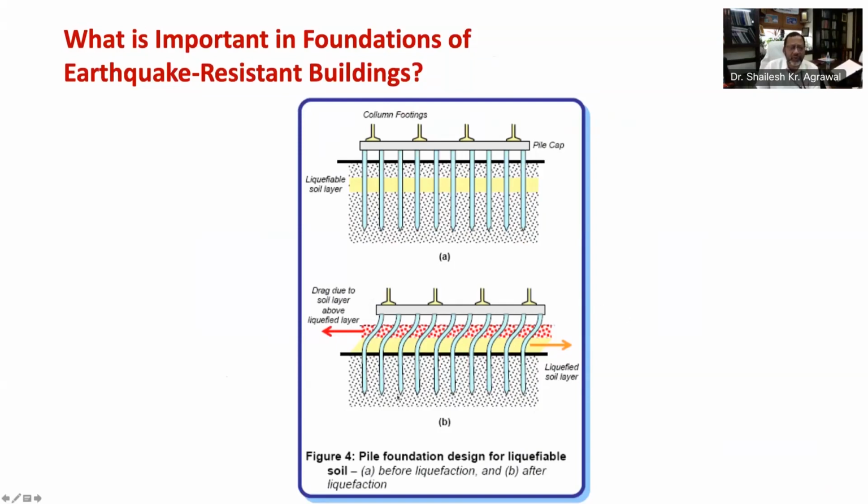In case of lateral spreading, investigation beyond the property boundaries of the building under consideration may become necessary, especially when plots are small. Also, lateral thrust offered by liquefied soil layers must be included in estimating force demand on foundations.